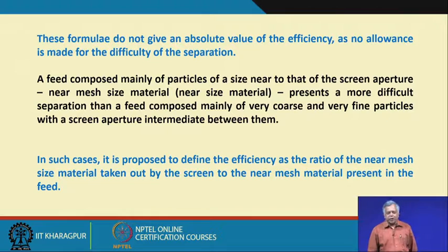And as we discussed about the near size material, here we are thinking of only two particle classes, that is, coarser than your aperture and finer than the aperture. What will happen to the near size particles? And how did you ensure that your screen is properly maintained and the screen surface apertures are properly made, and then what is the feeding system, what are the material flow characteristics? So how difficult is that?